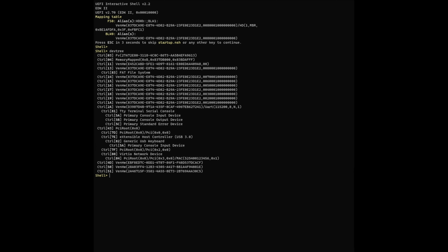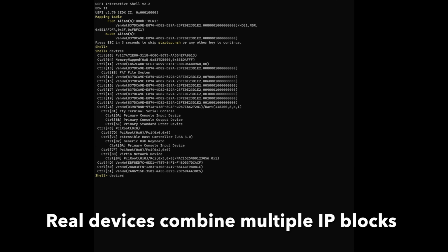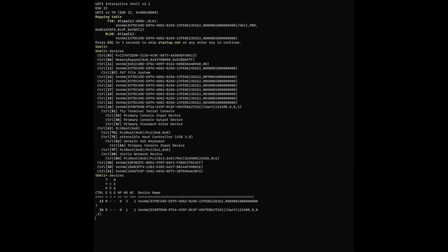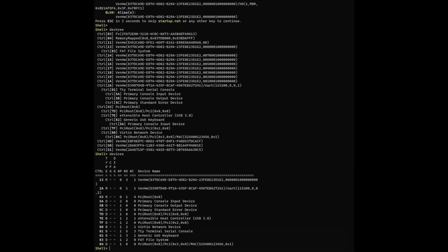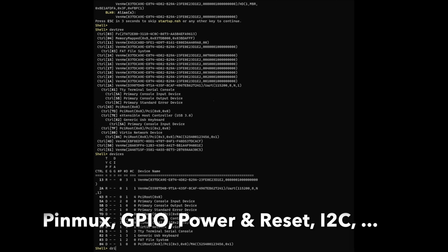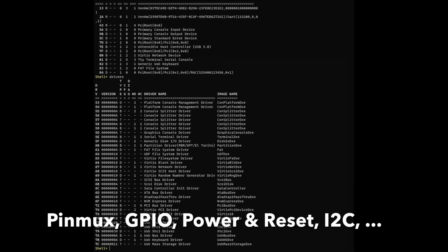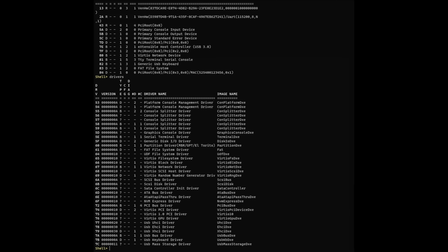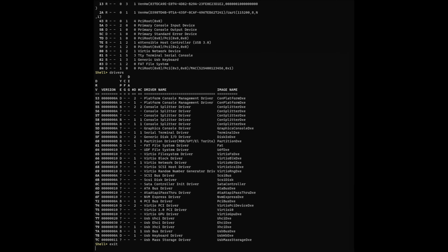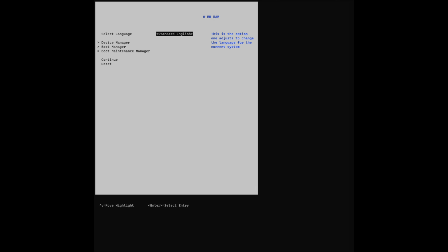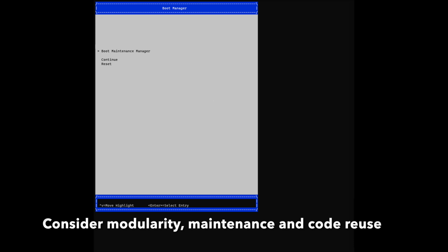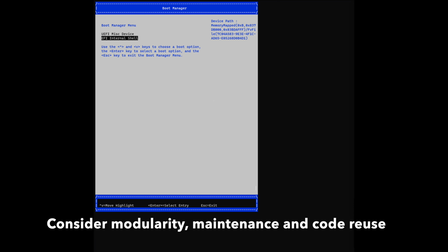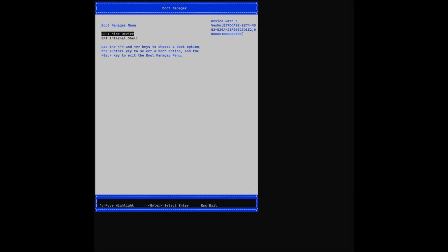Consider an onboard video device consisting of an LCD controller, video decoder, and multiple outputs, such as an HDMI encoder on an I2C bus. And then there are assorted clocks, pin muxes, reset signals, and power regulators to contend with. It can get hairy, and you're looking at a monolithic beast of a driver or at figuring out your own layering. And what if you need to target several board or chip variants with different wiring with a repeated set